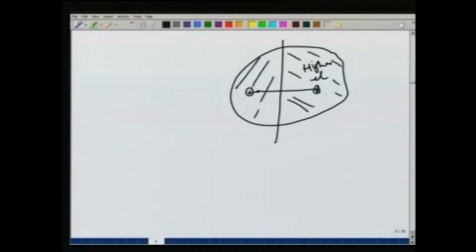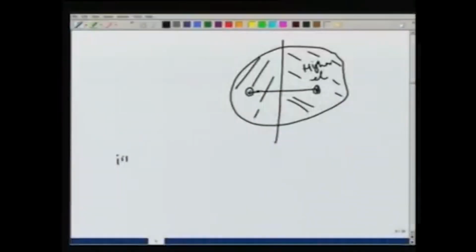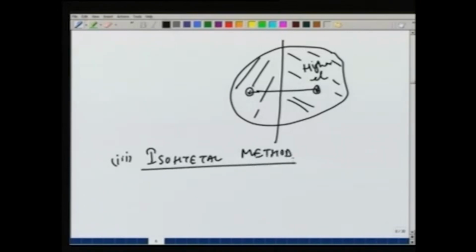It will not account for the topographic variation and therefore, rainfall variations within that area. So, the third method which we use accounts for this possibility also and it is called isohyetal method, in which we use the rainfall values at each station also in dividing this area.